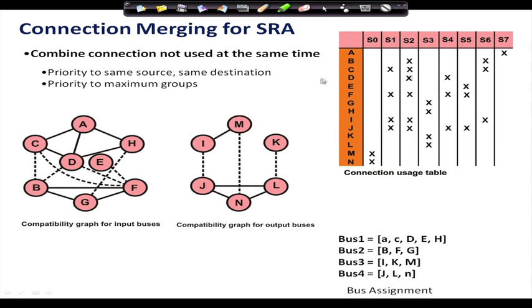Two distinct connections, say for example, A is active here, look at this table, A is active here and C is active in other states which are disjoint, right. So, A and C are compatible. What about A and B? A and B should also have been compatible, okay, but I mean C and D, are they coming at the same control step? No, in two different states.